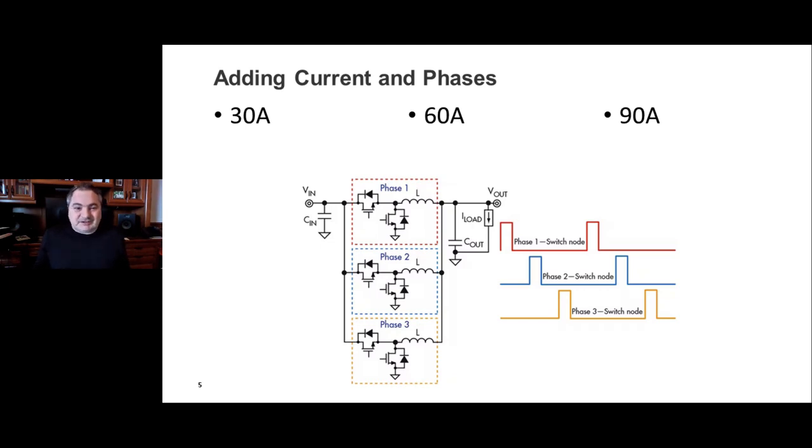It's not actually a glitch. It's probably the worst case situation where, because you've hit a pulse, you've done a transient load test on your power management device, but you've caught it at its moment of weakness. Now, those moments of weakness increase as you add phases. So there's lots to think about here.